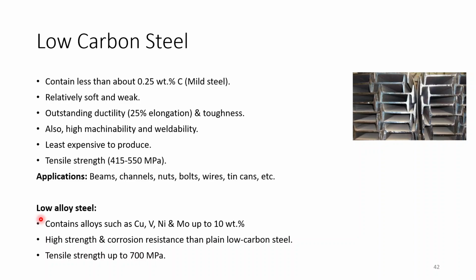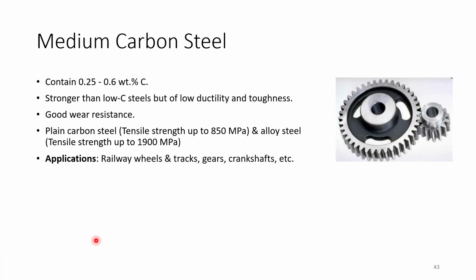In case of low alloy steel, it contains alloys such as copper, vanadium, nickel, and molybdenum up to 10 weight%, giving higher strength and corrosion resistance than plain carbon steel. Their tensile strength is also up to 700 MPa.